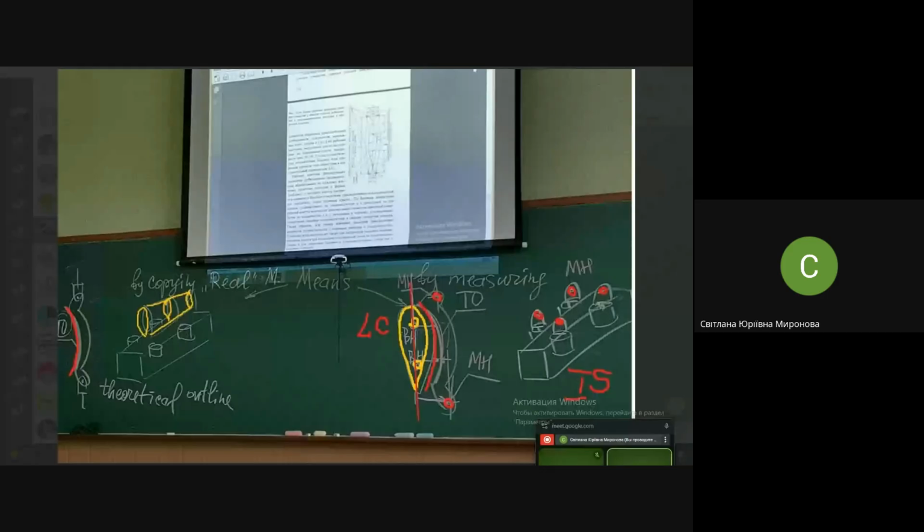On the left, I'm afraid to touch it or it will jump the text again. On the left, we see a yellow real object. This real object, for instance a mounting standard, looks like the skeleton of some wing or fuselage or whatsoever. And contours of this real object will be copied onto elements of the jig. And moreover, elements of the jig will be placed, assembled in accordance with this yellow object.